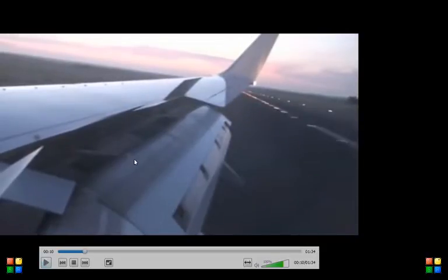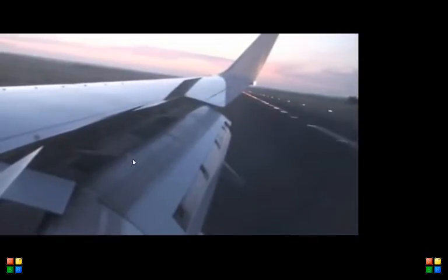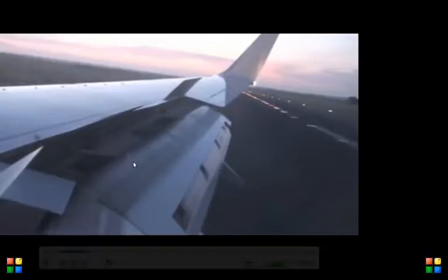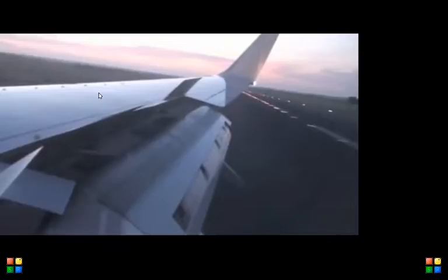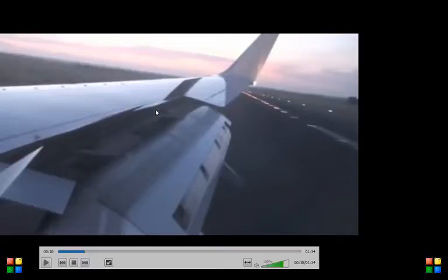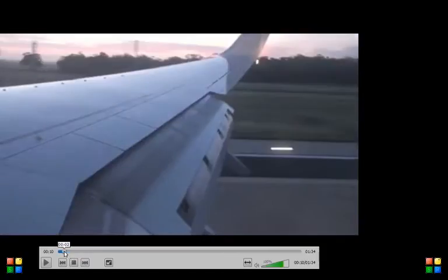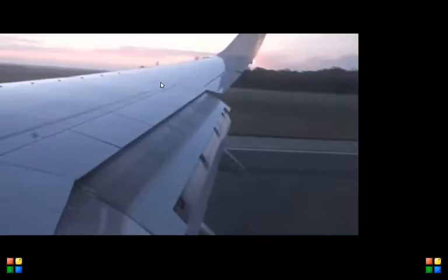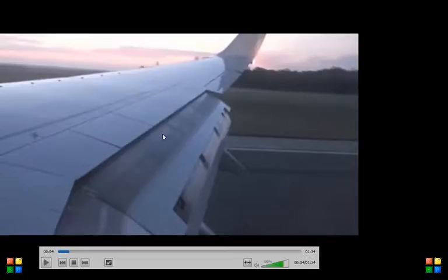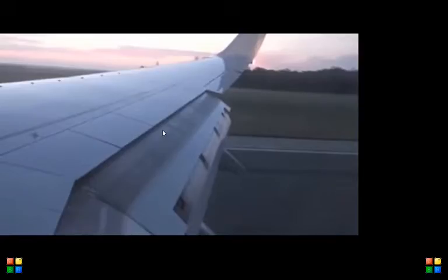And they serve two purposes here. They create drag force, and drag force directly slows the aircraft. But also they reduce lift force, and once the lift force is reduced, the entire weight is carried by the wheels, and that makes the brakes more effective. So they use the brakes just like a car to slow down. In this case, the spoiler operation is automatic, so the pilot doesn't have to turn on spoilers manually. As soon as the wheels touch the runway, the spoilers are deployed automatically.